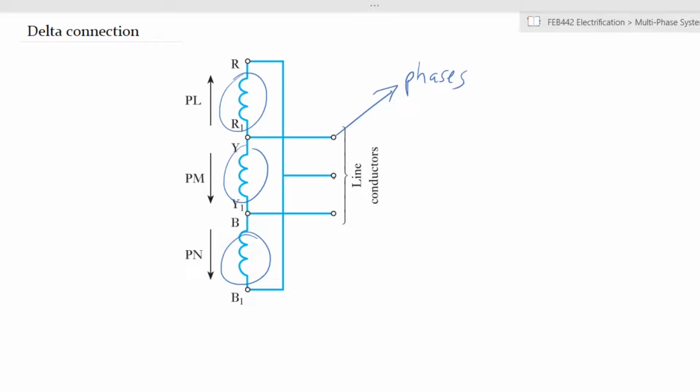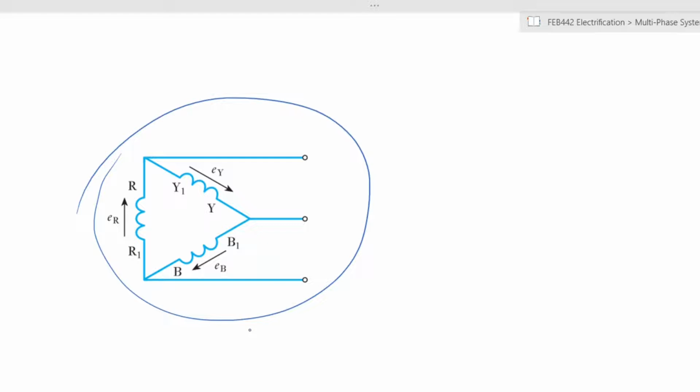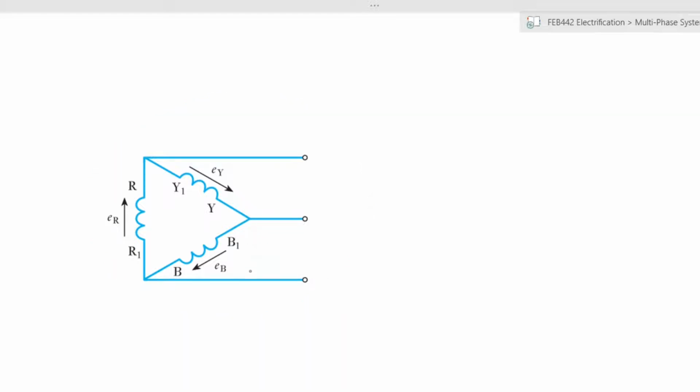These are the different phases of each of them. And that's why we say we have 3-phase power. Another way of looking at it would be if you were to connect them in this configuration. That's why you call it a delta. You have one winding, the red that we initially started with, connected to the yellow, and at the same time connected to the blue. And the blue and the yellow are connected to each other, and you have your phases that look like that.